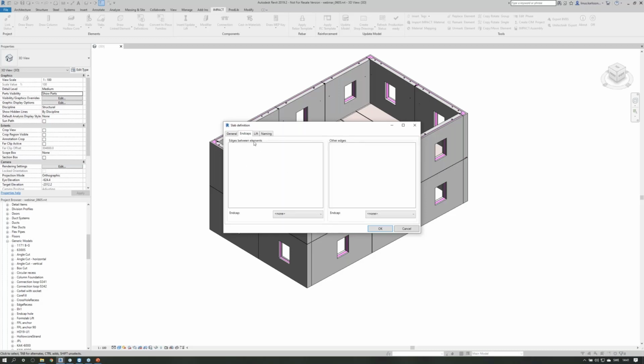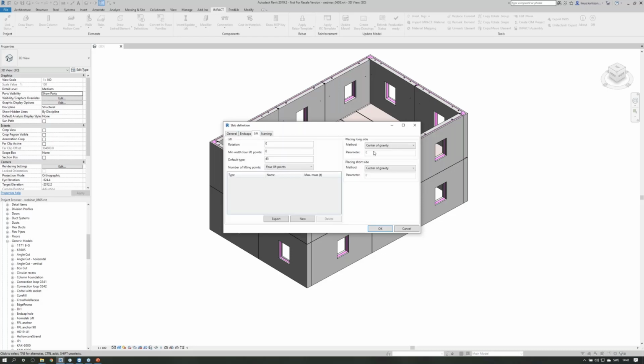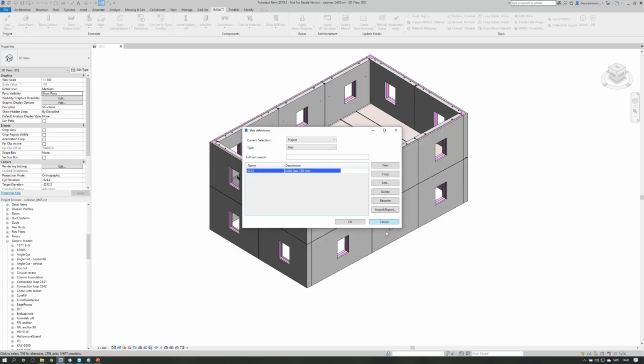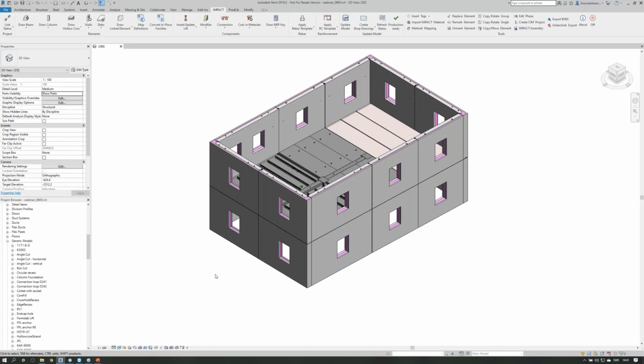Then we have specific settings for slabs if we want end caps to be inserted automatically. The lifting is similar, so you set up the rules, 2 or 4 lift points in this case. You add the families for the lifts with the capacities and so on. And for the slabs, you don't have the bracings since they are not used there. So there are similarities, but some things differ. And this naming tab is basically the same. So this is basically the system families.